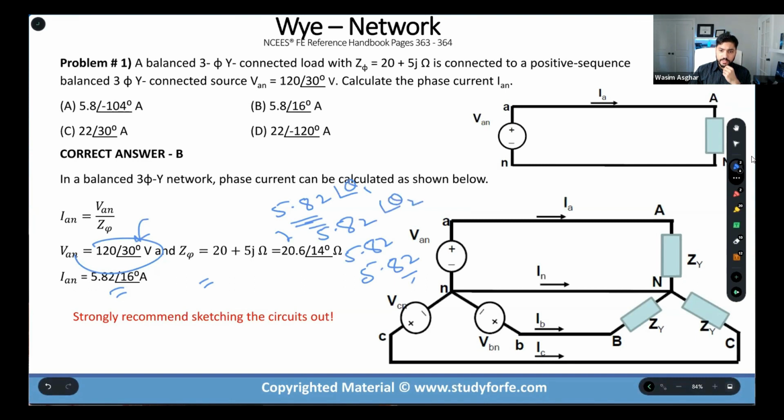This is theta1, this is theta2, this is theta3, this is theta4. If you took the shortcut while solving this problem, you'd have to redo the problem by taking the phase angles into consideration. So a tip, a suggestion, is whenever you're dealing with 3-phase systems, single-phase systems, transmission lines, in fact anything, always include the phase.